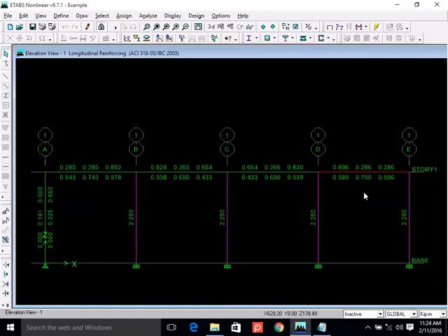Now you need at the bottom 0.3975 inch square total reinforcement. If you decide to use number 4 bar, then number of bars at bottom equals the area you need, 0.3975, divided by area of one bar, which is 0.196. So can you please quickly do the math?